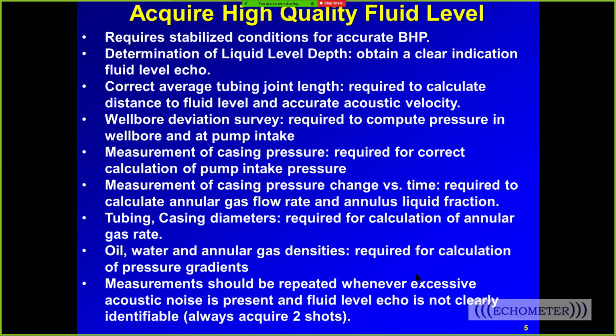So you won't see a hole below the liquid level, but you will typically see that the liquid levels are the same height in the tubing and casing if there's a hole. And with the well on pumping, it won't move up the tubing as it pumps. So those are two indications of potentially a hole.